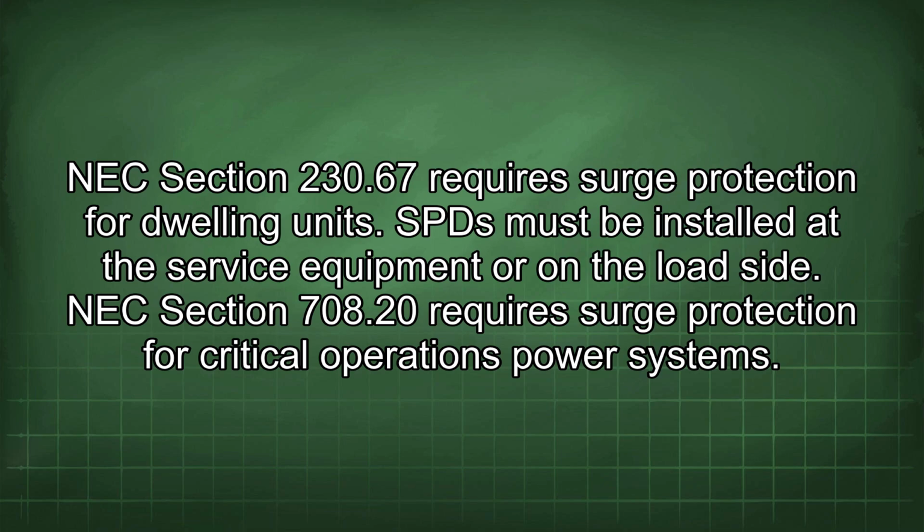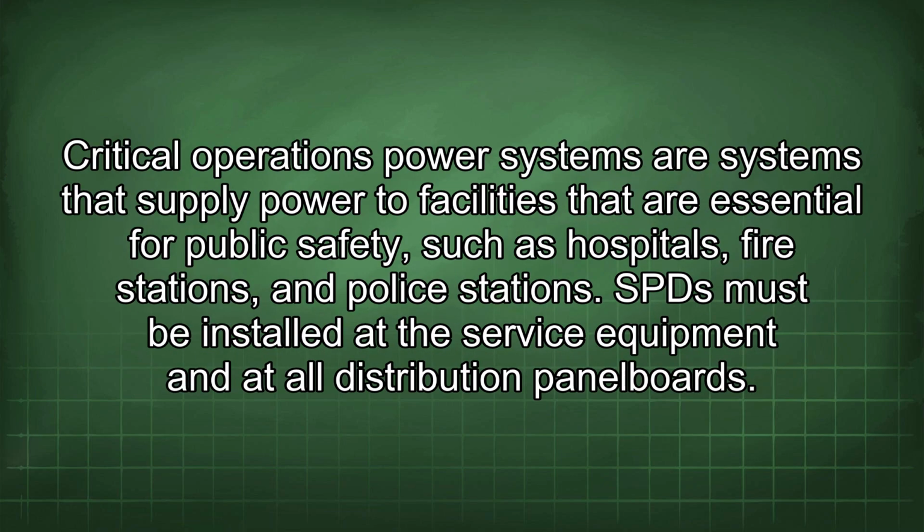NEC Section 708.20 requires surge protection for critical operations power systems. Critical operations power systems are systems that supply power to facilities that are essential for public safety, such as hospitals, fire stations, and police stations. SPD must be installed at the service equipment and at all distribution panelboards.